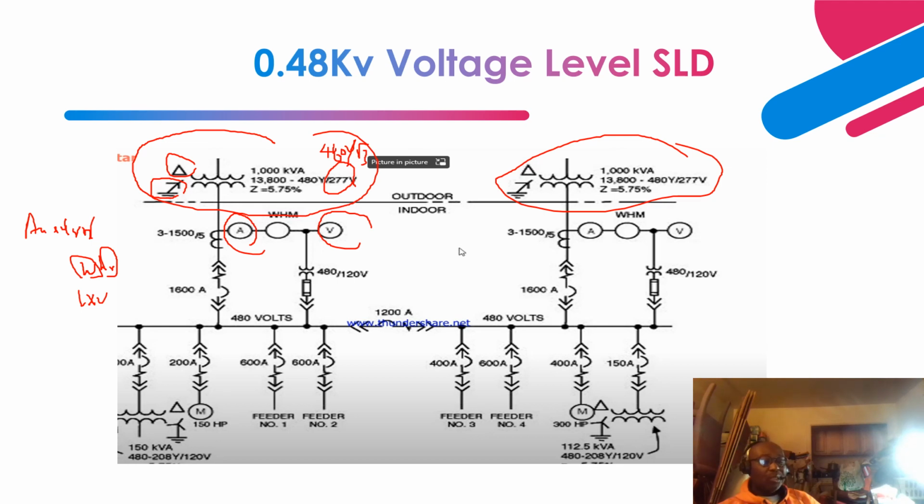Okay, so you are able to synthesize the amperage from CTs, dedicated CTs that are in the phase and bus. So probably on this feeder over here, you have CTs that have been wrapped around that feeder. So this one we have three CTs, right? One in each phase with a rating of 1,500 to 5, right? So the ratio is 300, right? So you have three of them.